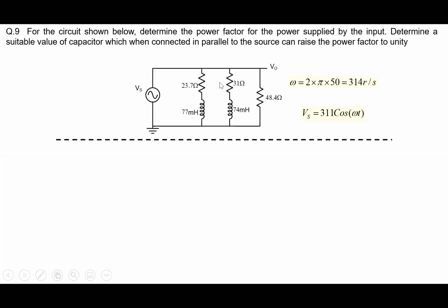And the reason why we are focusing on the power factor, just for the sake of discussion, just imagine that you had in the house just an inductor. So assume that this is 0 and this is 0, and this particular resistor is not there. So you have only an inductor inside the house. Now, of course there is a voltage and there is a current flowing. But what is the power factor? Because you have only an inductor, the angle between current and voltage is 90 degrees. Power factor is cos of 90, which is 0.